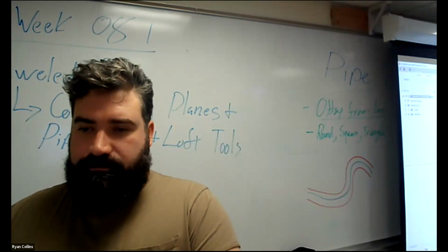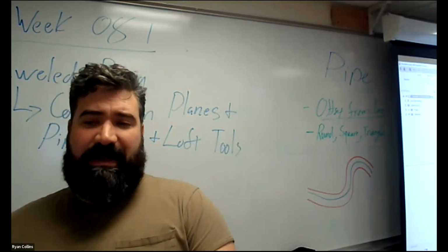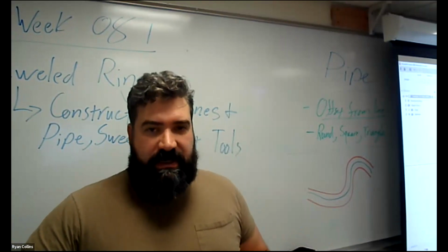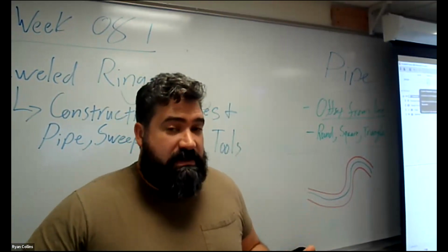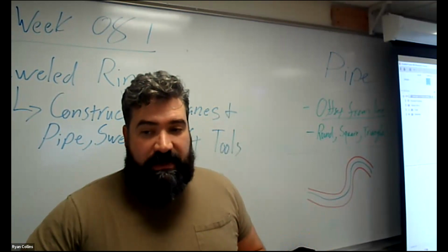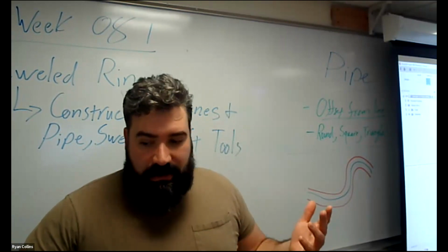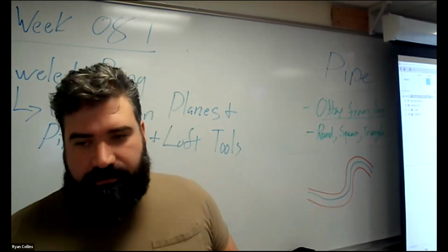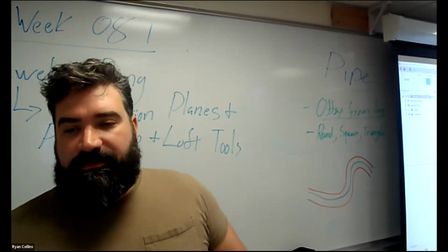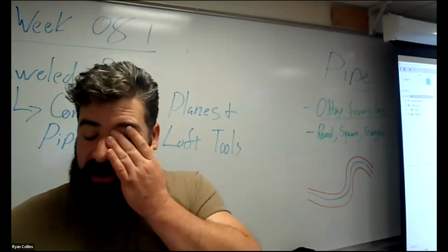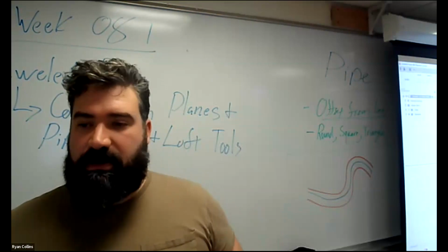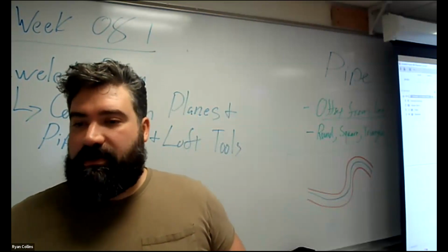All right. So like I said, depending on how big you want to make this, you might want to scale this up. So in this case, say I make this about 2 millimeters wide, I would probably expect to make this at least 22. Probably go larger than that. You play around with this. For this project's sake, or for demonstration's sake, I'm just going to make this a bit larger. Let's say 30. All right, there you go. Big enough. Okay, finish sketch.